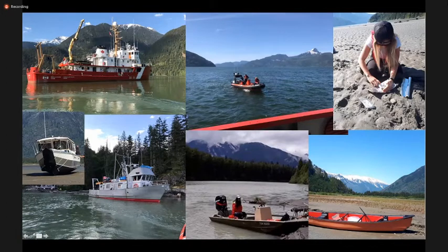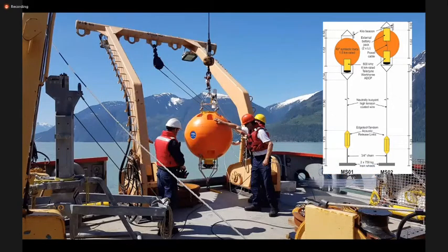The thing I'm going to focus on here is the direct measurements that we've made of flows, and we use these little yellow instruments here called acoustic Doppler current profilers, and these are suspended above the seafloor usually. They shine 4 beams down, and based on the energy that's backscattered within the water column and changes in the Doppler shift intensity, we can understand some proxy for the amount of sediment that's suspended in the water column by these flows, but also create a 3D velocity profile.